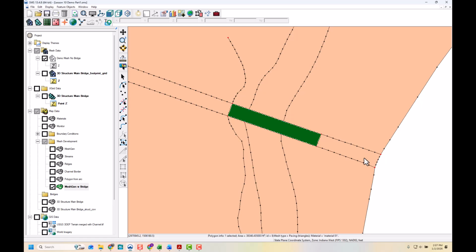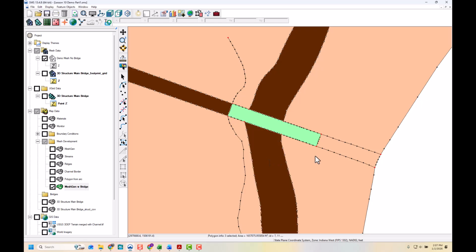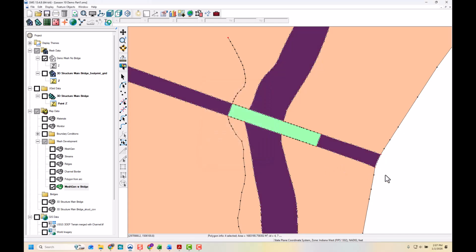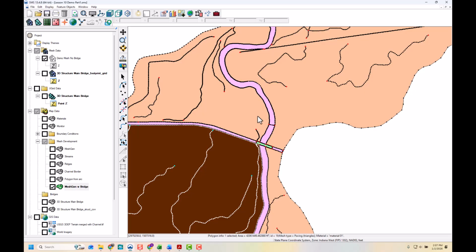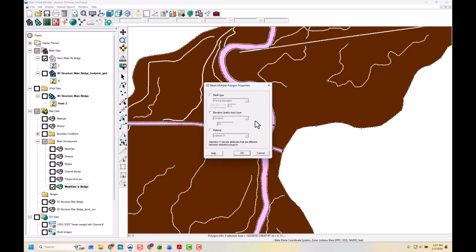Click OK. And now for these surrounding polygons that I had set as patch previously, I can hold the Shift key and select all of those. Right-click and set those attributes back to patch. Okay, and then also, looks like my other polygons all around here were impacted, and those were set at a constant paving density with a target size of 200 feet.